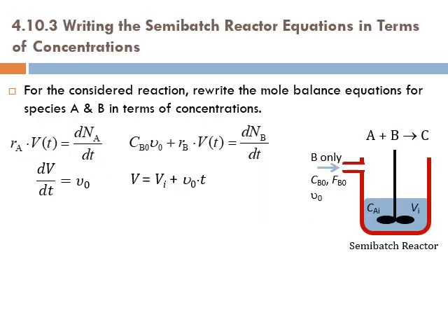Okay, so we said we can write the mole balances in terms of concentration if I want, or in terms of number of moles, as we did, dNA by dt, dNB by dt, which is the easiest thing to do. Or we can also introduce X, but of course, if we use the conventional X, the ordinary X, the answer will be wrong, right? Because X, the way we know it, is wrong during an unsteady state operation. Therefore my preferred way of solving these equations is to keep them as number of moles, dNi by dt.